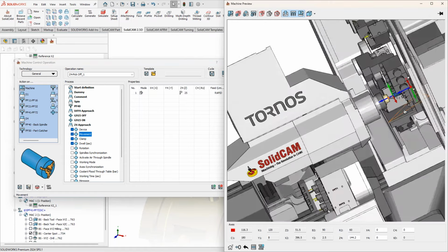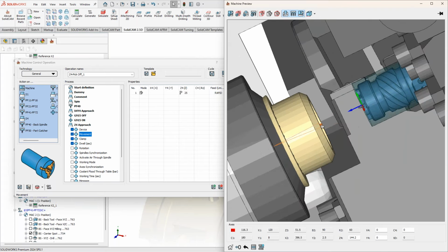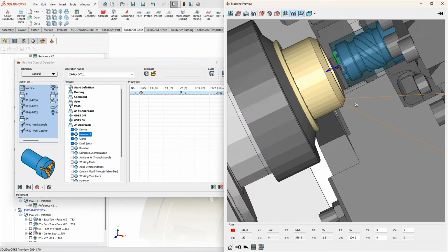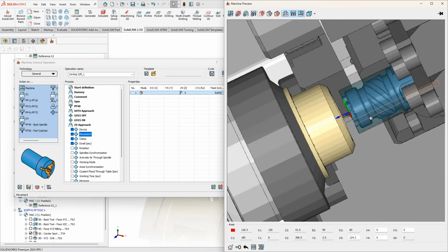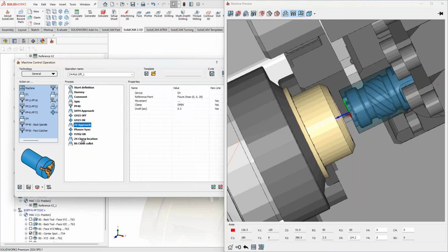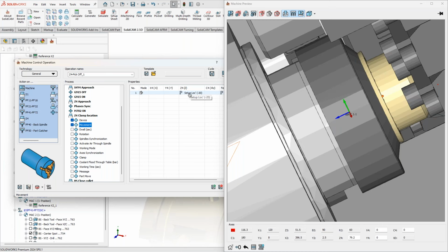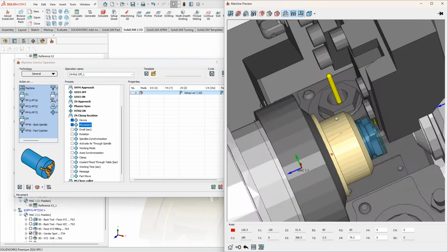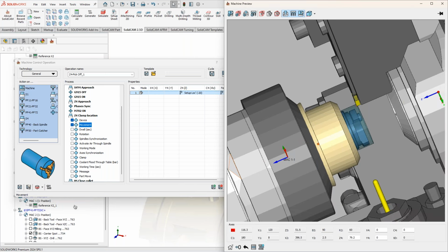25 will still be 25, but now our point is over here. So now I can change this to a safer value, no problem at all. The same thing applies to the clamp position: I can go to my movement and my setup location is now updated. You can see that the value was previously 40, now it's -20, very perfect, everything is the same. But now it is different because now I can generate G-code.